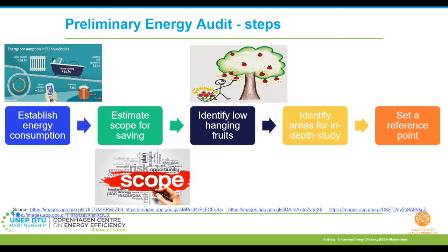The next step is trying to identify low-hanging fruits, most likely the easiest areas for attention. Something like identifying the type of light fittings, how many there are, and how many need replacement with energy efficient fittings. Do you have occupancy sensors or motion sensors in place? How is the insulation of the chilled water lines or steam lines?